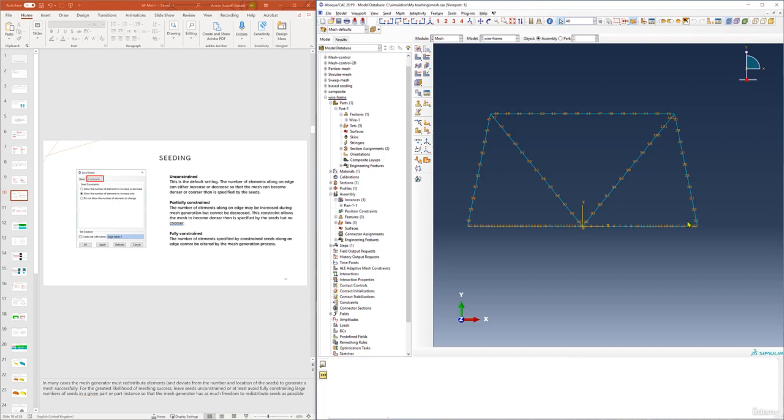We use this technique because in real life, when we do FEA analysis, some part of the geometry is more interesting. You have a higher stress concentration in those areas, so you will want more accurate results in those areas. And some areas are not really important, so you apply a coarse mesh. So this one will give you that flexibility to increase or decrease the mesh size on a specific area.